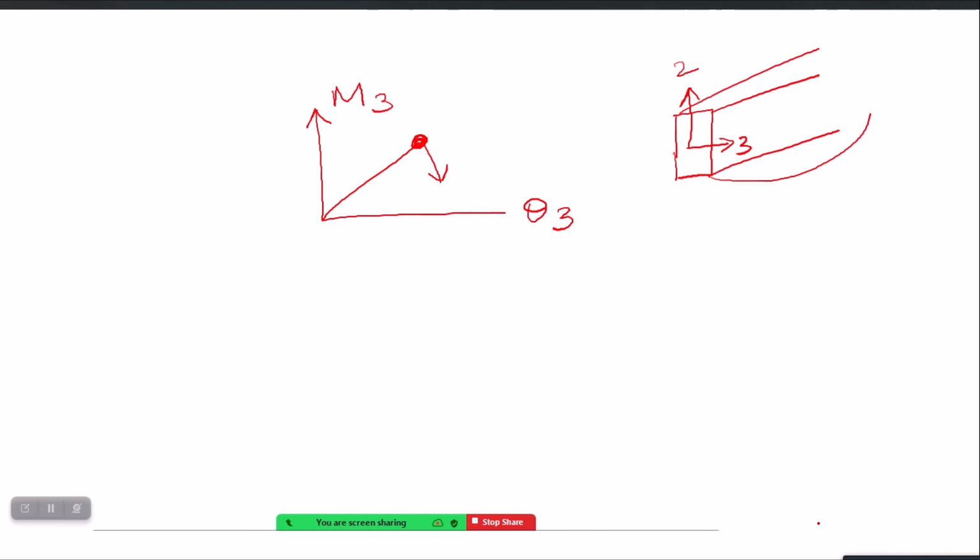You can see from the right hand rule that the primary bending of this beam will be in the M3 direction and theta 3 direction. So if you want to define a flexural plastic hinge for a beam, it should be M3 type, and the input required is a relationship between M3 and theta 3. But again, I will repeat that this initial elastic part you don't need to give.